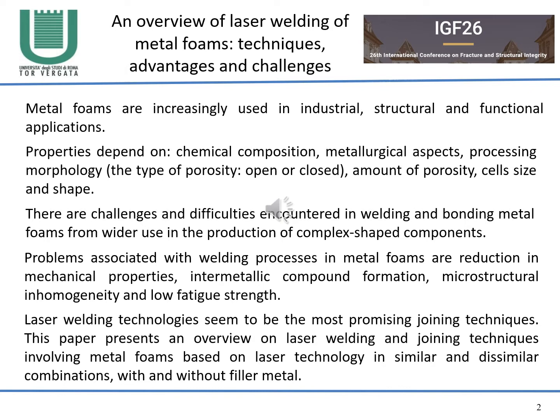There are some challenges and difficulties encountered in welding and bonding metal foams, which are widely used in the production of complex shaped components. Problems associated with welding processes in metal foams are the reduction in mechanical properties, metallic compound formation, microstructural inhomogeneity, and low fatigue strength.